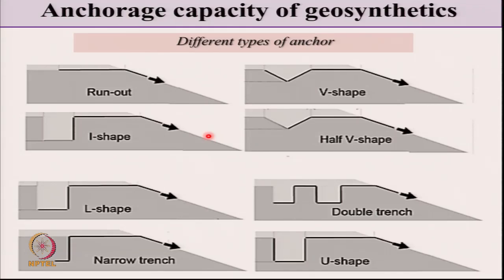And here are some configurations of trenches. Run out, just going down, L, narrow trench. Sometimes you may not be able to excavate vertically.